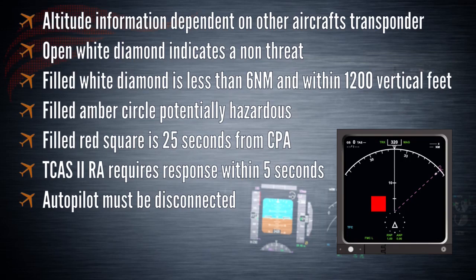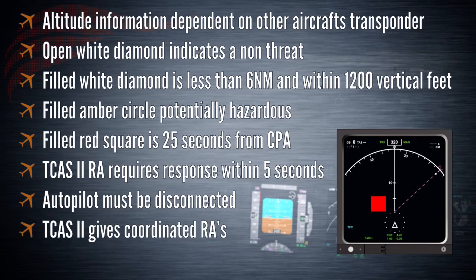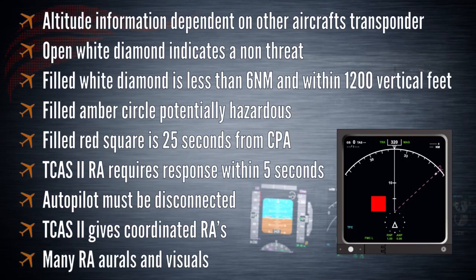As we discussed earlier, TCAS-2 is capable of coordinating resolution advisories via the Mode S data link. This is dependent on the intruder aircraft also having an operational TCAS-2 installation, but is effective in ensuring that the resolution advisories are compatible with one another and will not worsen the situation. There are many resolution advisory orals, and visual commands on the PFD vary depending on the type of advisory triggered.